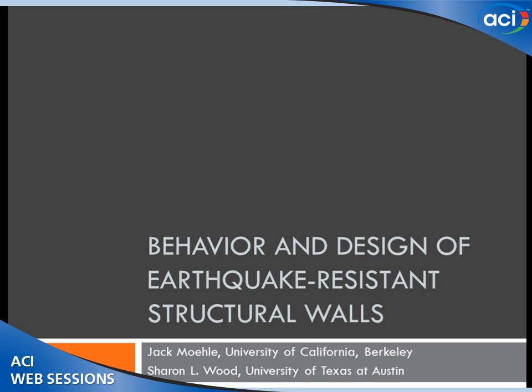We think that the inelastic demands are pretty low. And so for those buildings, these shear strength limits of 10 roots f prime c are fine. But in other kinds of buildings where the demands might be much higher, it's not 100% clear that these limits are always going to be the right limit.